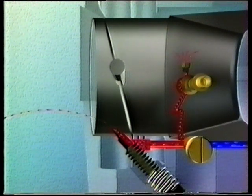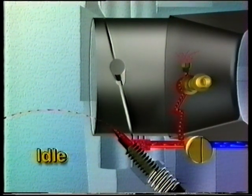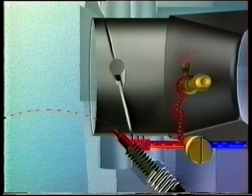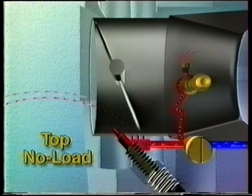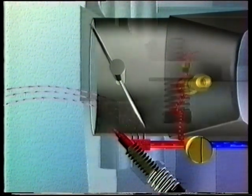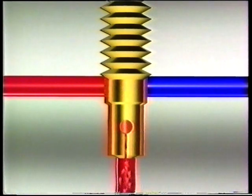The pilot jet restricts the fuel coming up from the bowl into the idle circuit as engine conditions change. At idle, the fuel delivery is not restricted very much, because a very small amount of fuel is needed to maintain idle speed. However, when the engine moves to top no-load speed or becomes lightly loaded, the pilot jet begins to affect the engine's performance. The size of the pilot jet's orifice provides just the right amount of fuel needed to maintain the proper speed when the engine is lightly loaded.